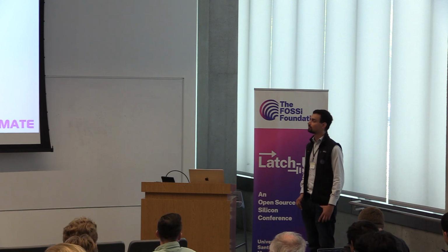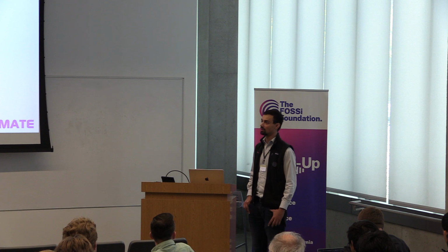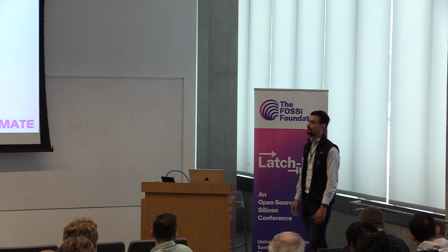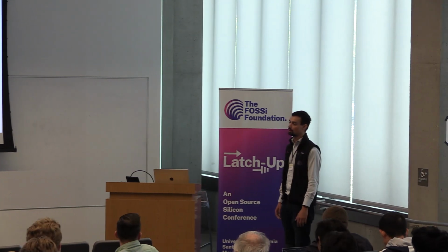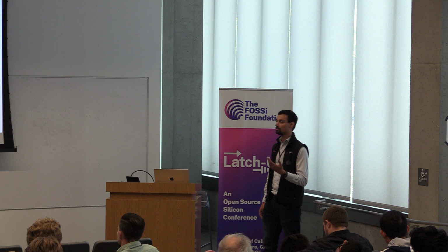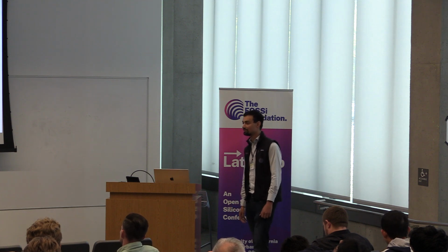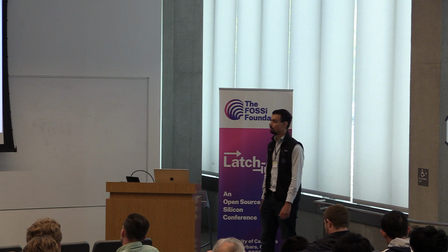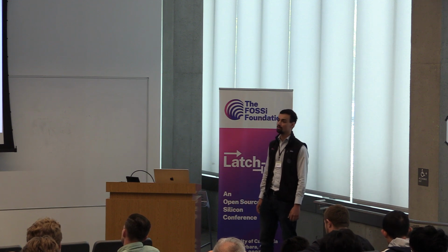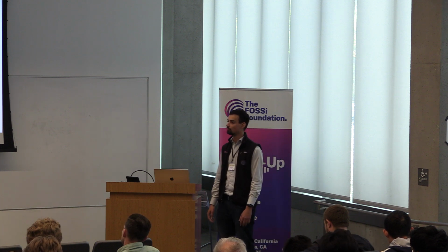Yes. Compared to most of the open source tools on the back end side, it's very mature, I would say, compared to all of them. It has basically full support for SDC, unlike some of the other tools like iEDA and OpenTimer, which is really great. So you can use it almost as a replacement for most commercial STA tools if you'd like. And it actually runs very quickly too. I've done some benchmarking and it compares favorably to a lot of other tools.